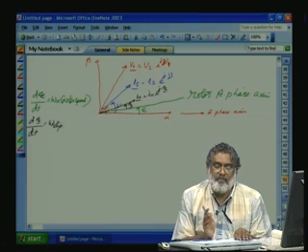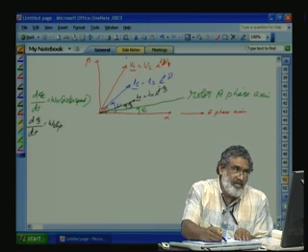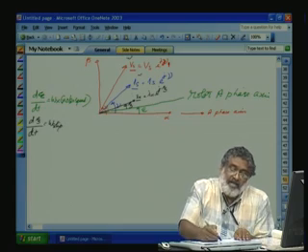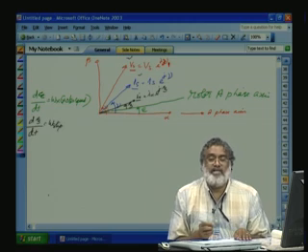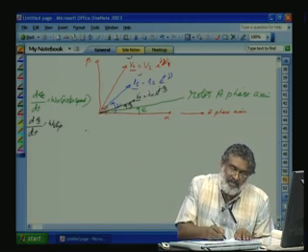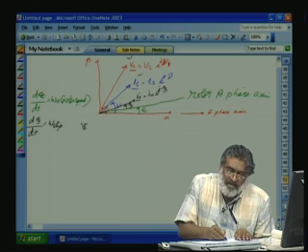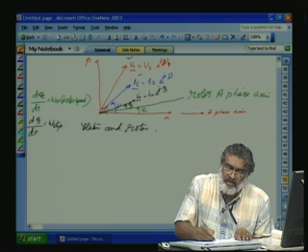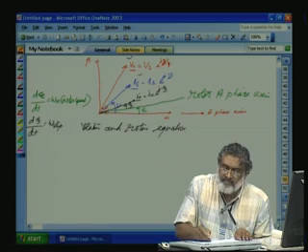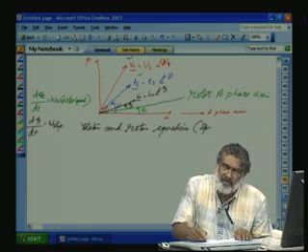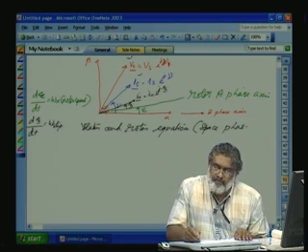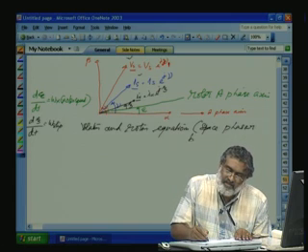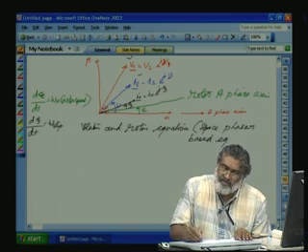Now, the relative position of the rotor voltage, stator voltage, stator current, and rotor current is known. So, let us write down the rotor and the stator voltage space vector based equations. This is space phasor based equations. We are not using the ABC components and alpha beta. These are all called space phasor or space vector based equations.